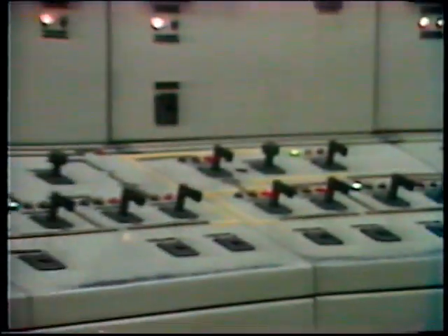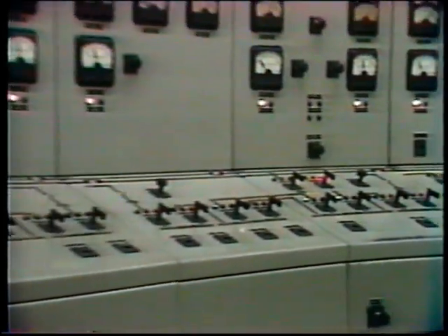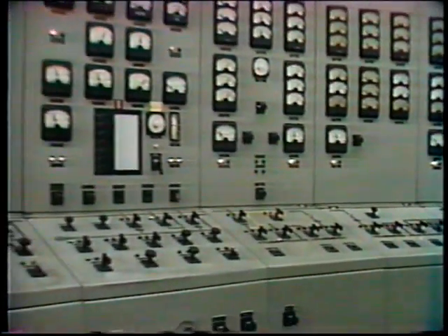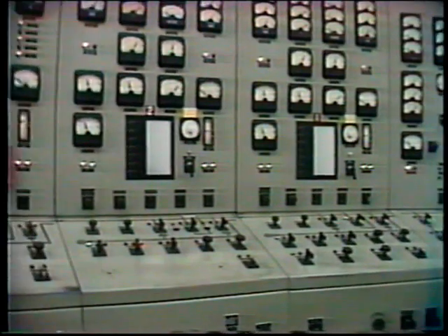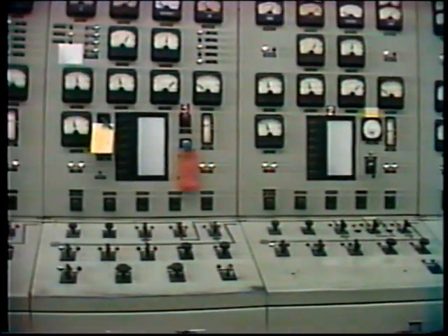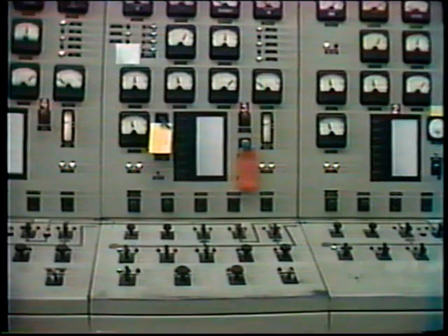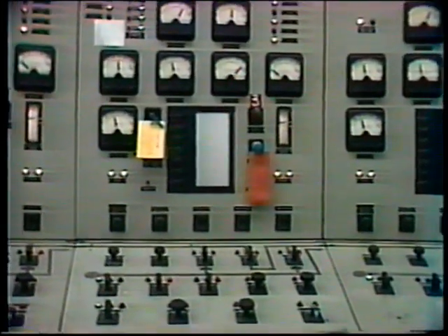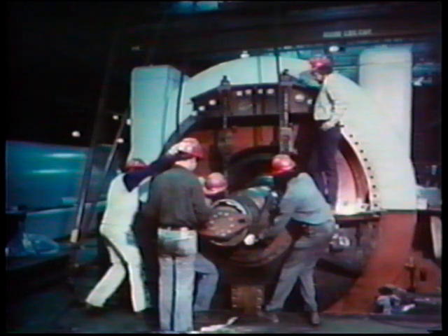Most manufacturers of large AC generators recommend that both the generator and its prime mover, usually a steam turbine, be disassembled and inspected every 3 to 5 years. So overhauling isn't done very often, but it is a job that you're likely to be involved with from time to time. So that you'll better understand how a generator is taken apart and inspected, we'll go through a description of an overhaul of a typical large AC generator. We'll concentrate on the major steps that must be performed during the overhaul.